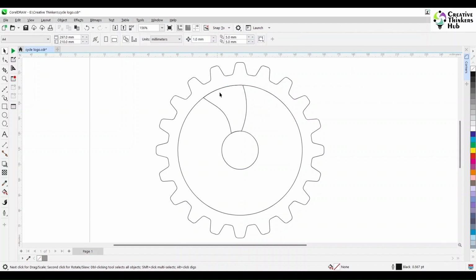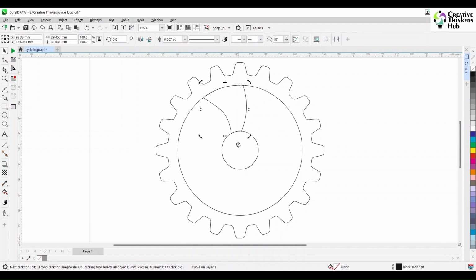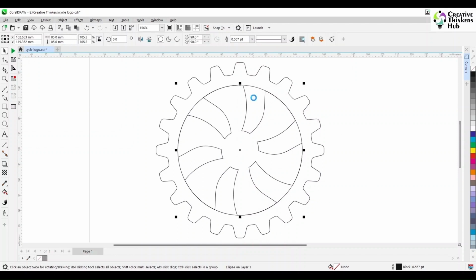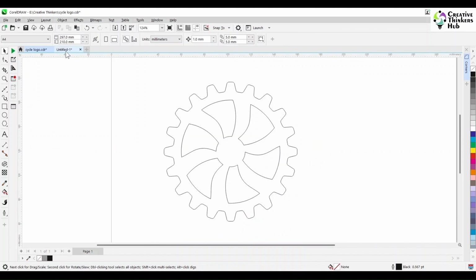So you get your perfect shape. Now make the center right to the center of the circle, press Ctrl and rotate it and left click, right click. So that's what you get, and then duplicate it all throughout. Now this circle that is 25, you make it 25.5. There's a reason for this, because these trims that we have done, they have a jagged edge. So if you don't want a jagged edge in your final output, it's better to make it slightly bigger. Now you trim everything and weld accordingly.